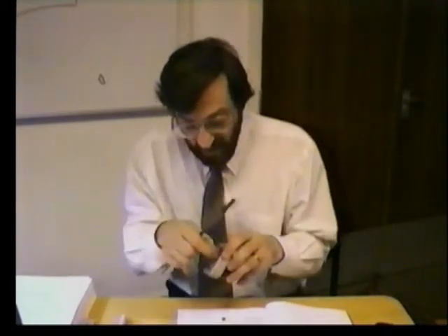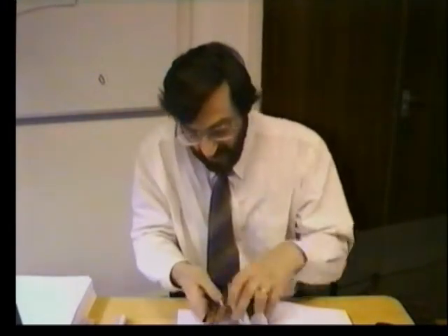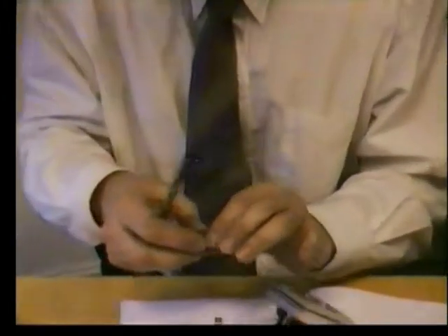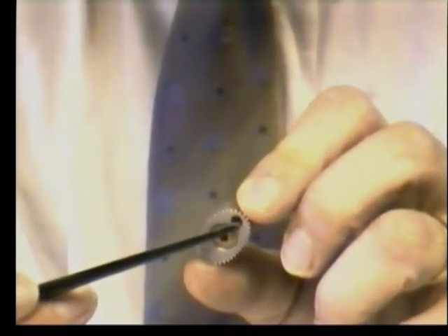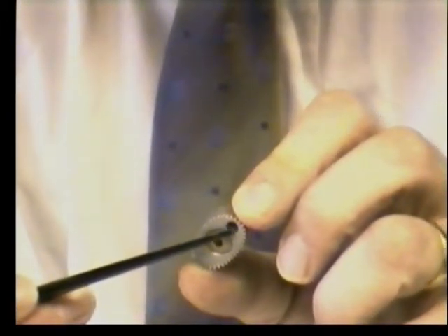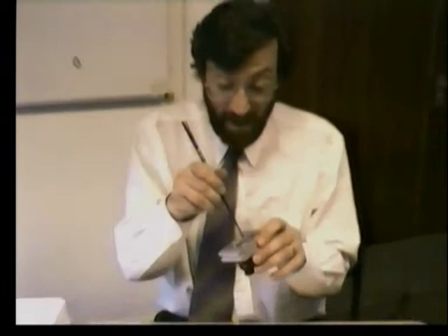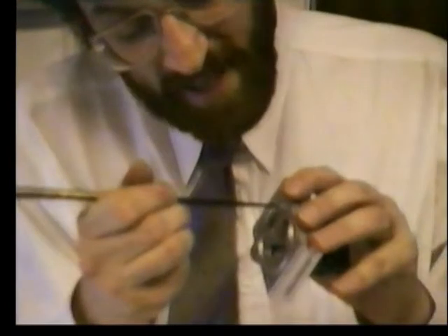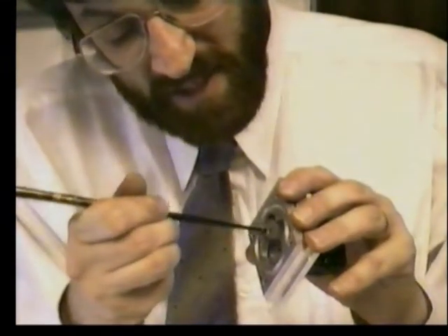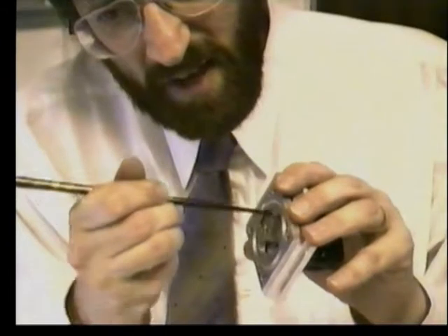Now, what we can't see, I'll just take out this little slug here and we'll move into it very carefully. Just there, that is a magnet, a permanent bar magnet. So what happens is that if we have a pickup like an electric guitar, that's all it is, every time that rotates, we have a magnetic sensor, in fact it's embedded inside, a magnetic sensor there, we can detect when that magnet flies past.